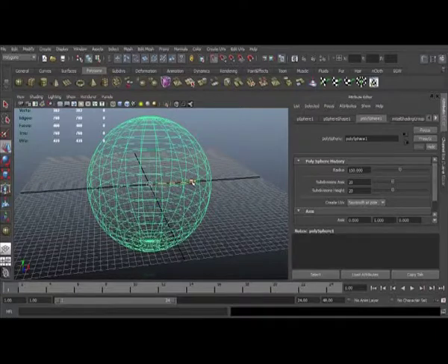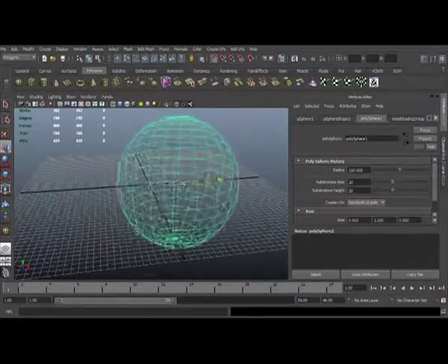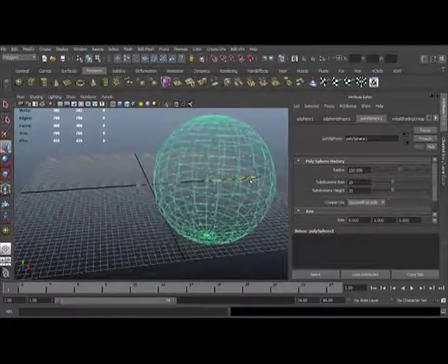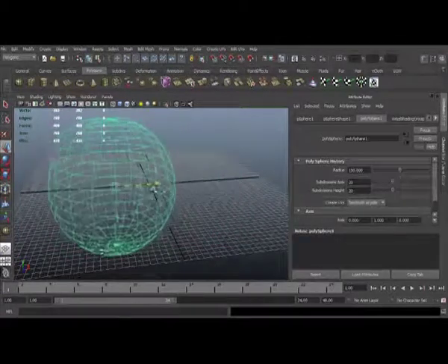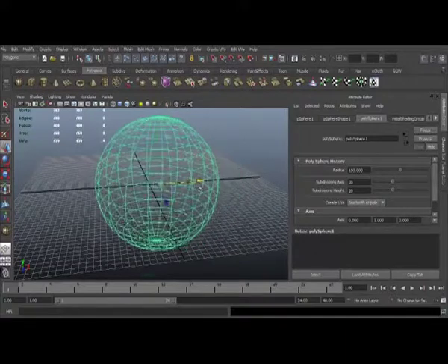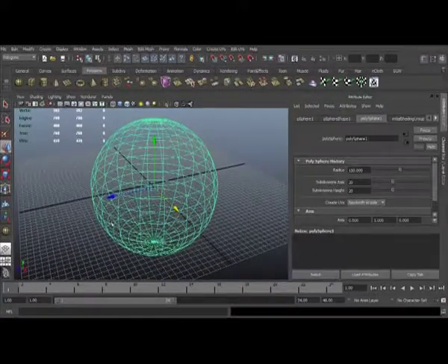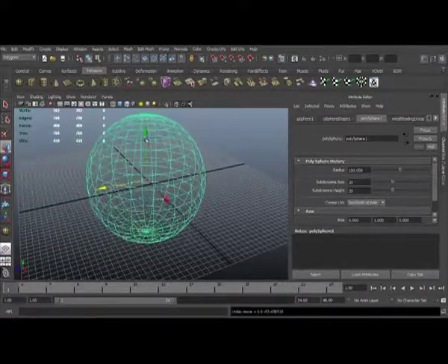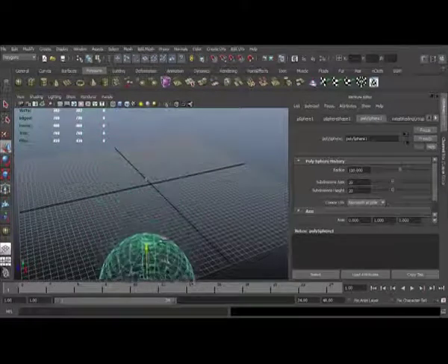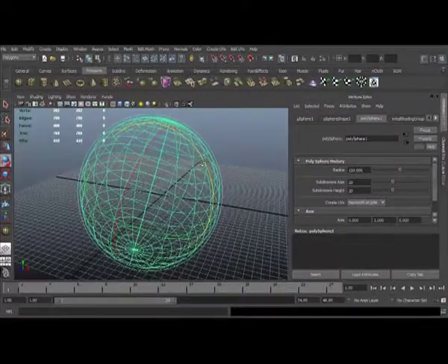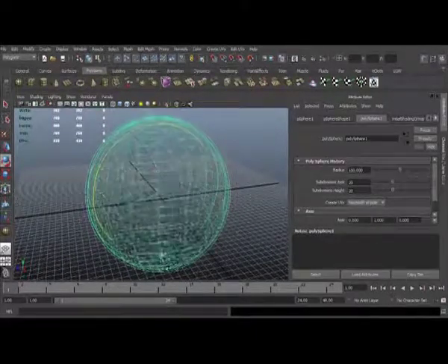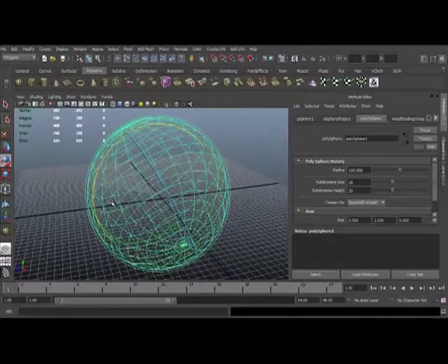Click the Move tool icon in the toolbox and then select the object you want to move. Maya displays a manipulator with 4 handles, one to move along each axis and one to move anywhere within the planes. Click on one of the handles as indicated in the figure. The selected handle changes color when active. The default color is yellow. If you double click on the toolbox icon for move, rotate and scale, you get an option for tools. None appear for scale, but at least an empty dialog box appears. A useful option in this dialog box is snap spacing.